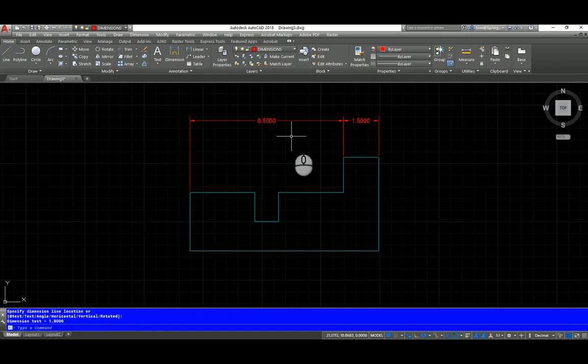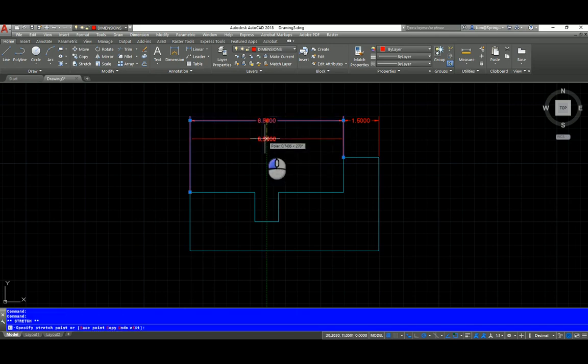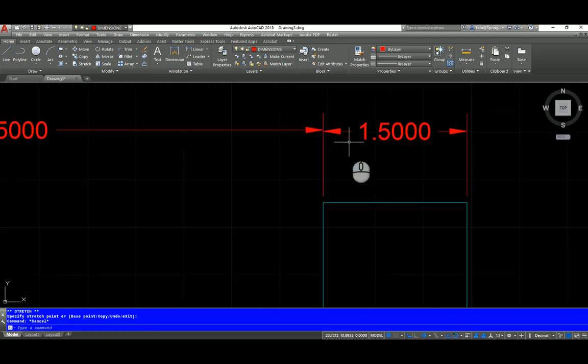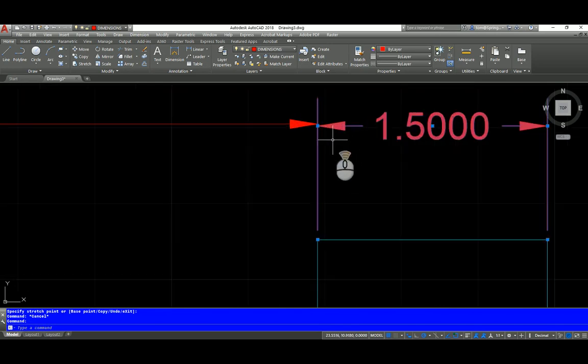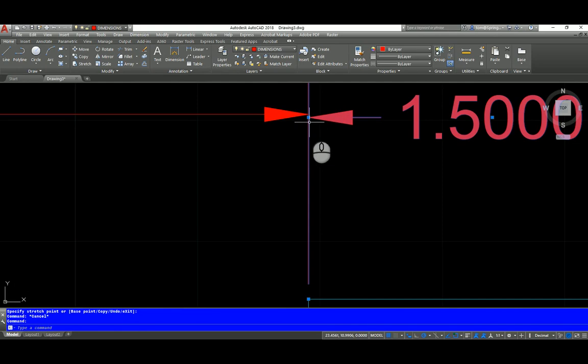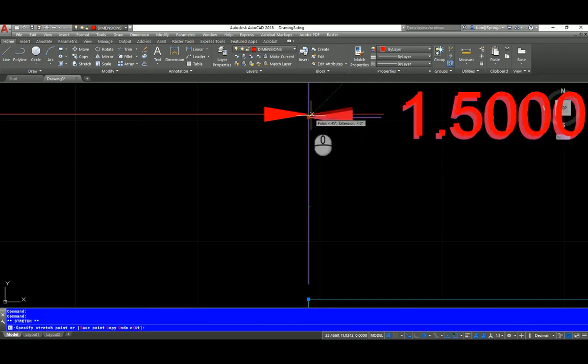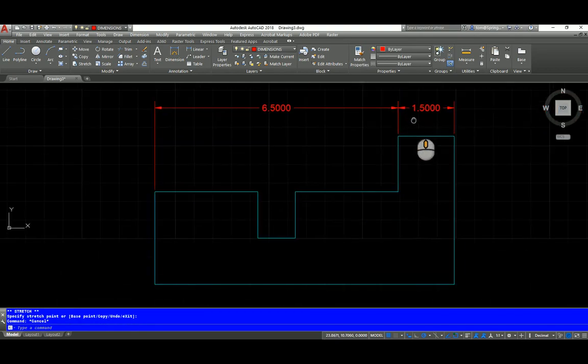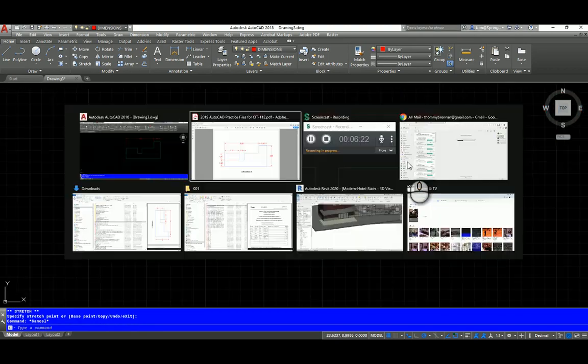And if these are not quite placed correctly, you can move the dimensions. It's not hard. You click on it, and you grab the grip right here, and you pull it down. And you put them where you want to. And these actually want to be connected, okay? A really cool thing about your dimensions, if I click on here, it's like the ring in, and Gandalf's telling Frodo about the ring. He says it wants to be found. Well, so do your dimensions. So you click here, you pull it up, and it snaps to that point right there. Boom. And that's how you can do that. So they actually want to align. You just have to tell them how. So that's how we begin to put in dimensions.